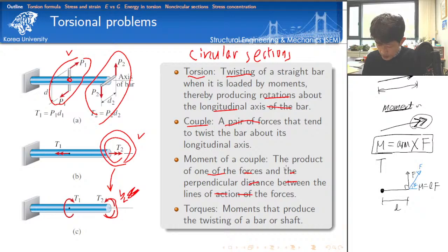Then in this case, the moment produced by this blue F is equal to, we have to consider only the perpendicular component. The arm length is L, and the perpendicular component of force is force times sine theta. Is it clear? As an extreme case, for example, what if you have a force like this? In this case, the moment produced by this force is what? The arm length is L, and the perpendicular component of force is F sine 0, so this is equal to 0.